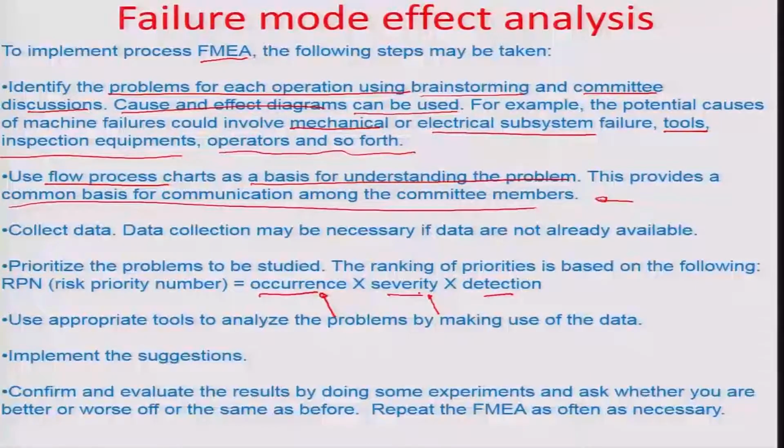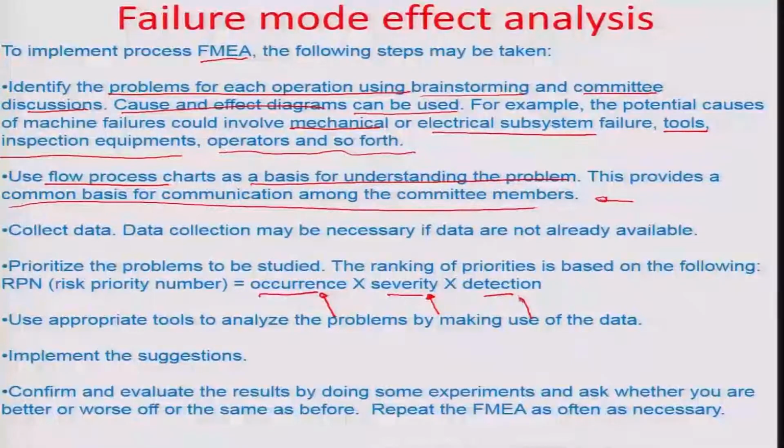Rating could be between 1 and 10 in a group of failures, or what the severity of a failure is relative to other failures which may be existing, again rated in a group of 1 to 10, and then the detectability of a certain failure mode, how probable it is that the failure would escape the notice of people who are involved in contributing to some kind of process deviation which leads to the failure.